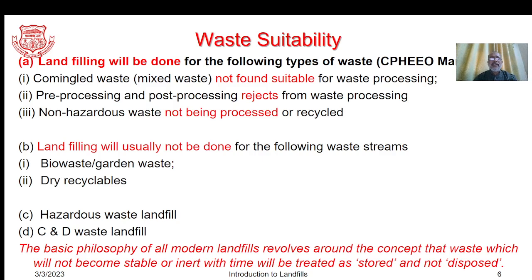Whereas, if we see the various operational constraints and consider the basic logic behind landfilling, we must not go for bio-waste, garden waste or dry recyclables. As discussed previously, bio-waste and garden waste can be subjected to composting, vermicomposting or even biomethanation operations.